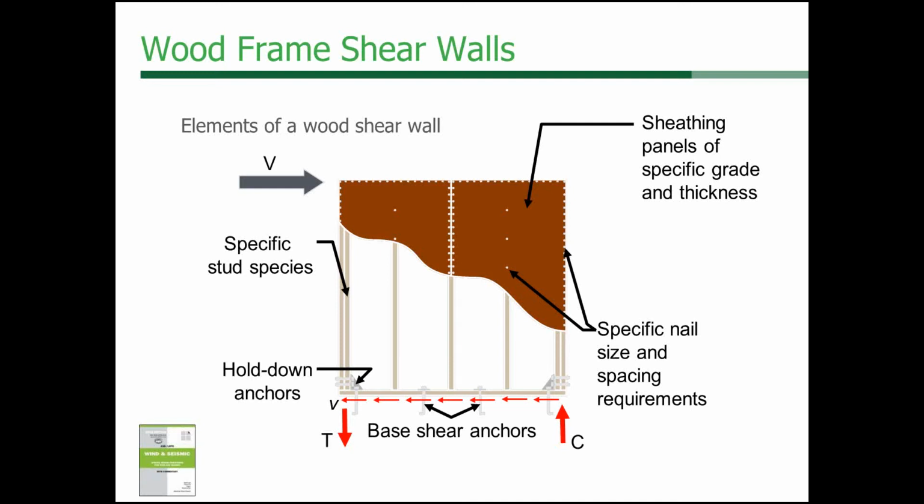But the one thing also I wanted to point out is, even though it was shaken 3 to 4 times, there was some lengthening of the period as a result of the multiple loadings. But still, it had a period of roughly 0.2 to 0.3 seconds, which is what we expect from ASCE, and that's what ASCE standards are based off of, which are straight from ASCE 7. So it was predicted to perform that way. They tested it. It did perform as it was predicted. And it's unfortunate that the video didn't work.